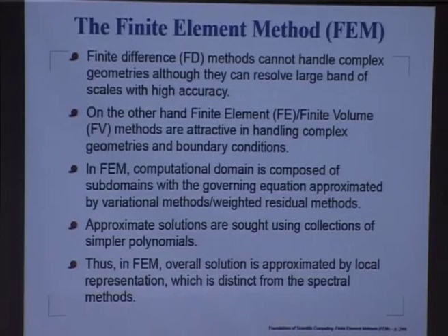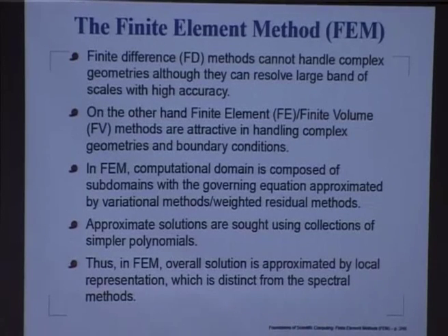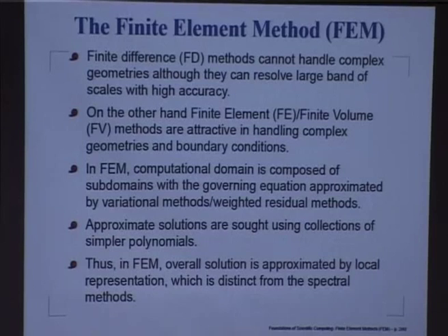So, what we are saying is that in FEM we will assume a form of the solution, which we will call the trial solution or approximating functions, and then we will plug it into the differential equation, and we will see that the differential equation will not be exactly satisfied.